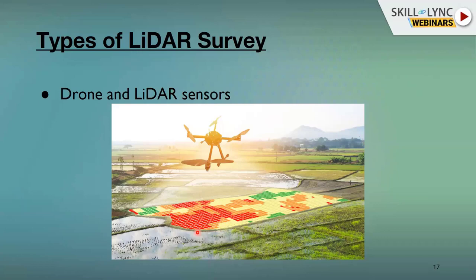Let's say if they want to cover a big city, like 1,000 square kilometers or 2,000 square kilometers, definitely they can't go for the drone lidar survey. Definitely they will prefer to go for the airborne lidar survey.